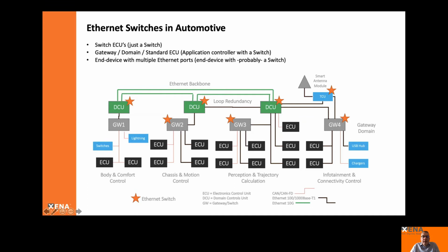So you can see that we are here working already with a complete Ethernet backbone based on a 10 gigabit interface, or 10 gigabit bandwidth in general. It's in green here. So you can see all 3 domain controller units are connected in this Ethernet backbone. We have additional redundancy in there for a gigabit link between 2 domain controllers, even if we have already redundancy in the Ethernet backbone ring.